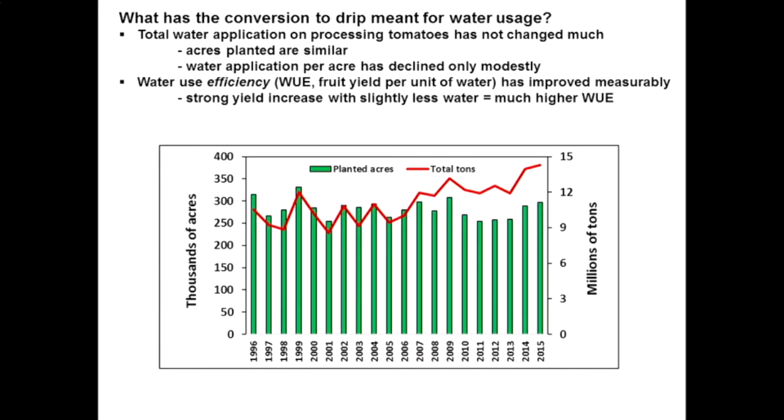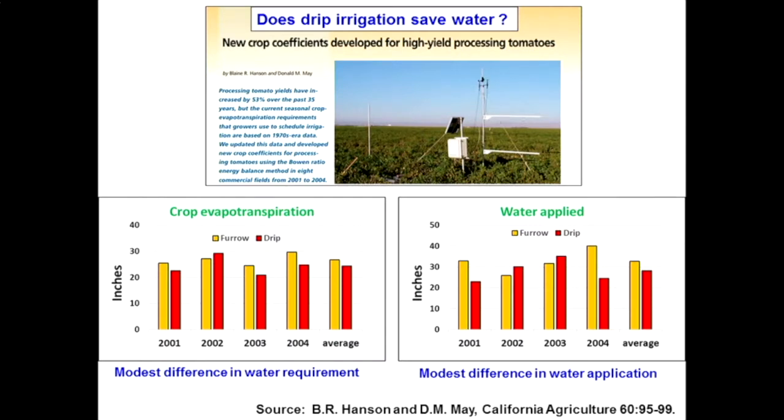So it's like looking at weeds and saying when they became water stressed, those weed plants would then want to set seed and become more fruitful. And with this drip irrigation experiment at Fresno State, it showed me at least that full-on watering, keeping that plant fully watered, matching ET made the most sense. Brought our yields up, and that's I think what's happened with our drip, better uniformly distributed water.